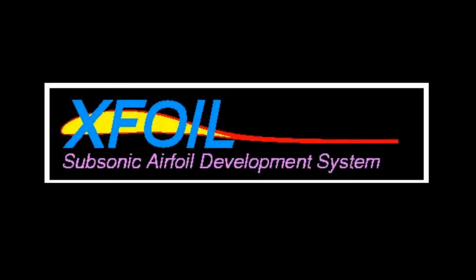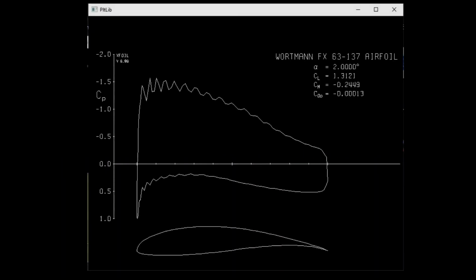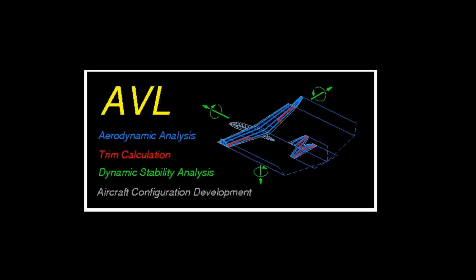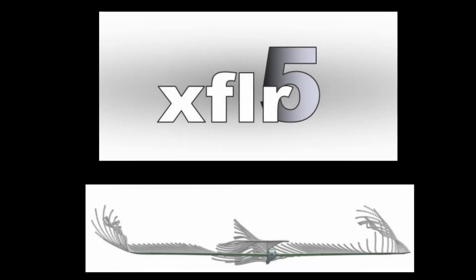Xfoil, on the other hand, is lighter and provides pressure distributions quickly because it's only 2D. But because it is 2D, it is limited to the profile with a trailing edge flap. There are 3D equivalents, AVL and XFLR5, which is mostly for planes, but apparently you can use it for multi-element wings, but you're better off using a finite volume method based software here.